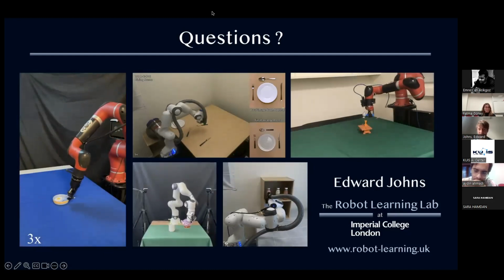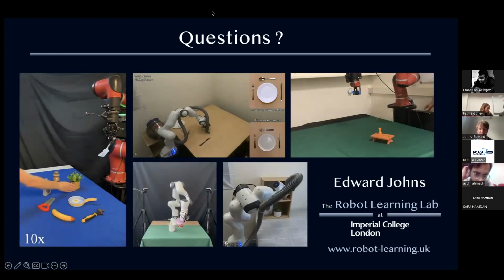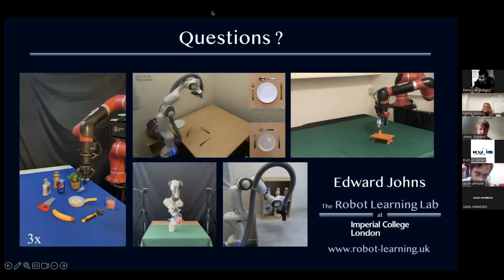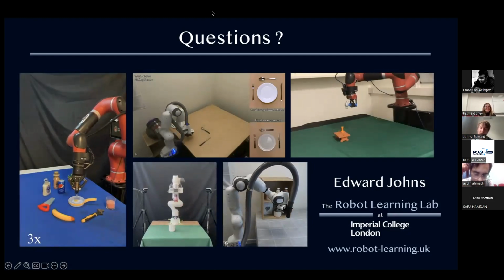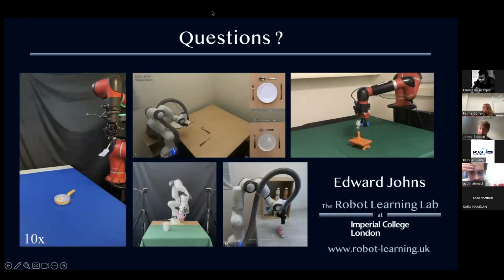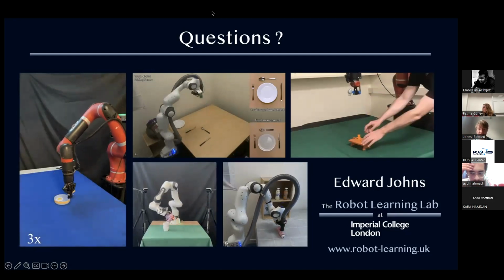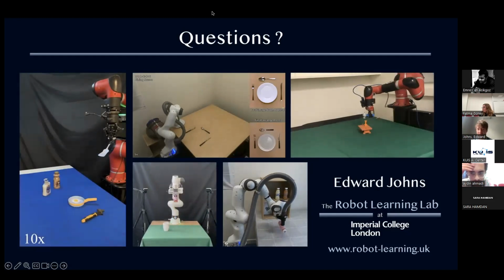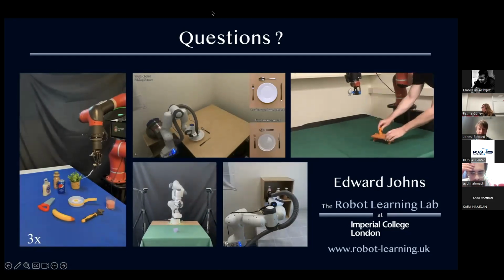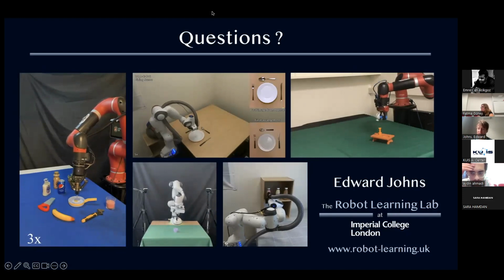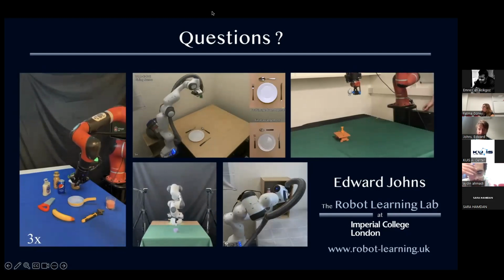So for example, with the video on the top where the robot is setting the table, we just have a very, very simple primitive for how the robot can pick up those objects. This robot has a suction gripper on it. And simply we just say to the robot, go to the middle of the object, apply suction, and then lift the object up.